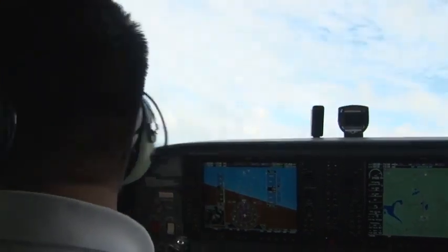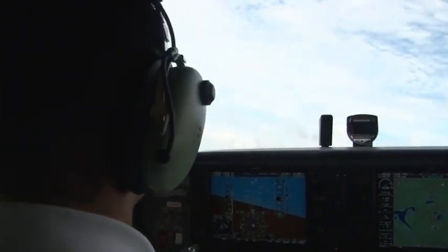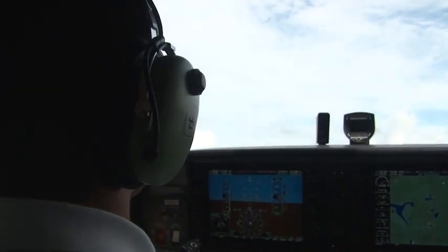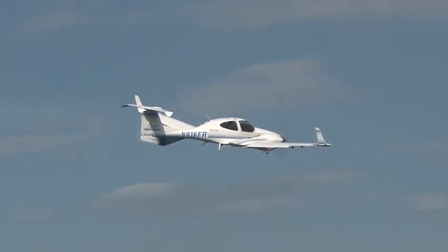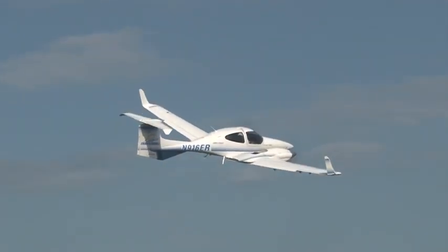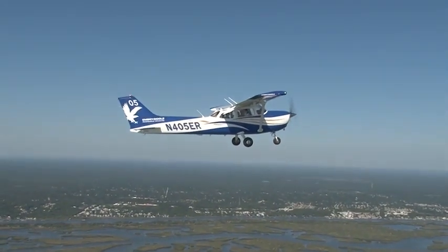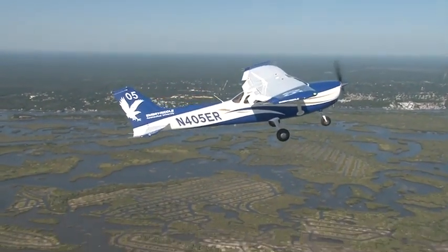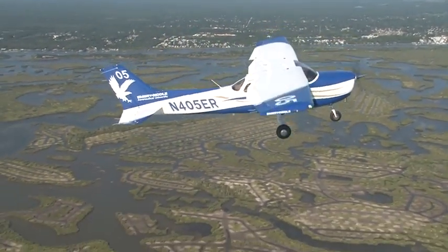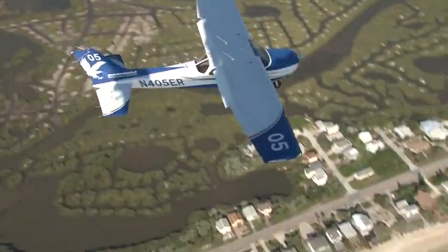Generally speaking, there are only two ways a pilot can control the amount of lift the wings can generate: airspeed and angle of attack. The faster the airplane travels, the more lift the wings will generate. Similarly, the higher the airplane's angle of attack, the more lift the wings will generate. However, there's a limit to this angle. Let's look at this using a chart.